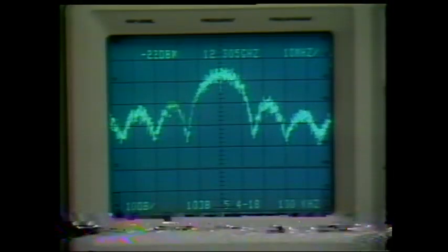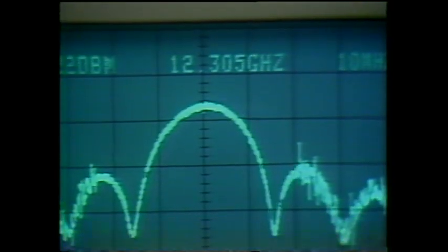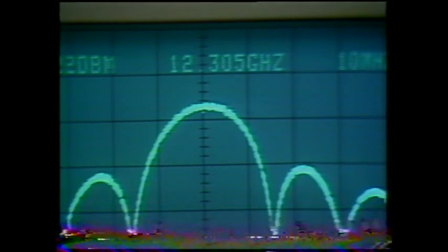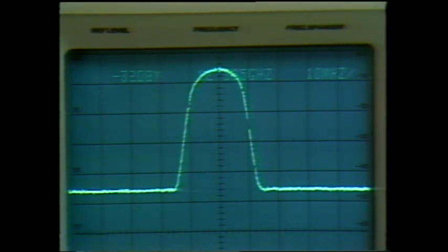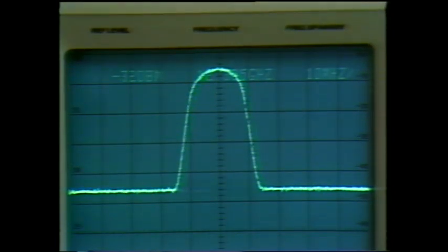The signal we'll be measuring is an 8-phase shift keyed signal, which looks like a sin x over x display. We can see this classical shape as we look at the output of the radio before the filter. We can smooth the display using digital averaging or the video filter. Now, to meet the maximum power output bandwidth requirements of regulatory agencies like the FCC in the United States, a filter in the radio removes nearly all of the side lobes. The loss due to filtering is usually negligible.